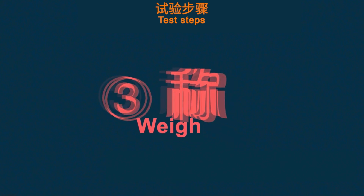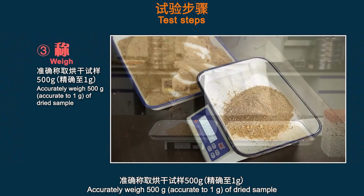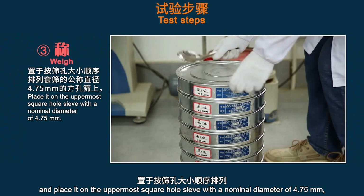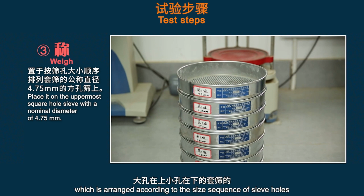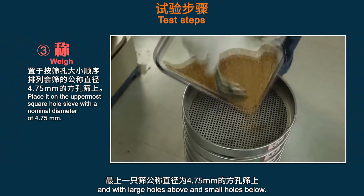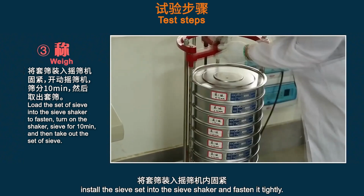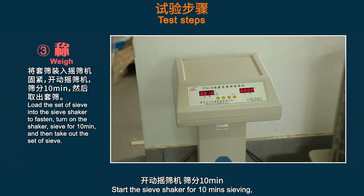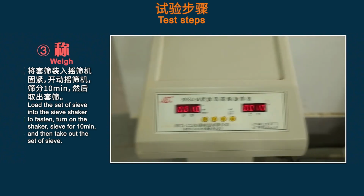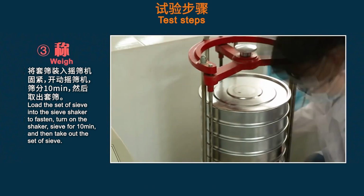3. Weighing. Accurately weigh 500 grams, accurate to 1 gram, of dried sample, and place it on the uppermost square hole sieve with a nominal diameter of 4.75 millimeters, which is arranged according to the size sequence of sieve holes and with large holes above and small holes below. After covering the sieve cover, install the sieve set into the sieve shaker and fasten it tightly. Start the sieve shaker for 10 minutes of sieving. And then take out the sieve.